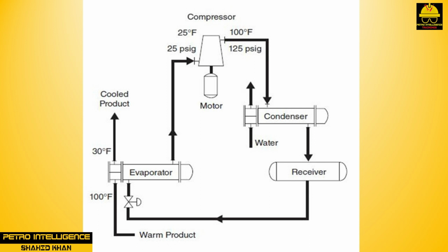Most large refrigeration systems operate at several levels of temperature and pressure, called stages or steps. Multiple stages are used because the application of several stages increases the efficiency of a refrigeration cycle and results in lower compressor horsepower. There are practical limits to the optimum number of stages. Generally, 3 or 4 steps are employed. It is a good design practice, because of safety considerations, to operate the first or lowest stage compressor suction at a positive pressure to establish the minimum operating temperature. The other temperature levels are set by the design of the particular system.